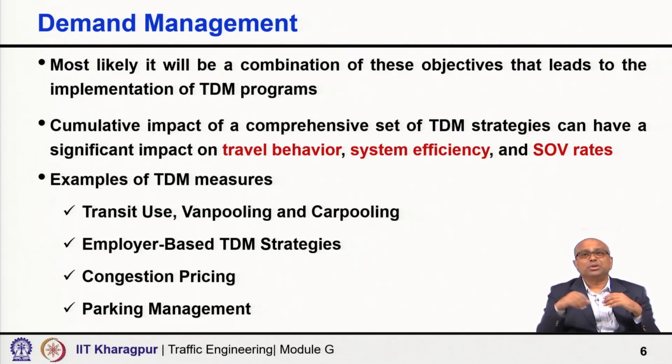But parking management is also part of traffic management and can also be linked with the TDM strategies, because depending on how you are doing the parking management, you are actually trying to influence the number of vehicles which are coming to the CBD area. So, that way you are also trying to influence the overall demand, and therefore, it can be part of demand management.